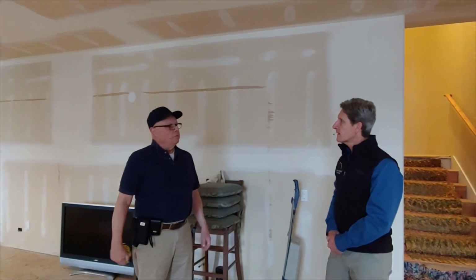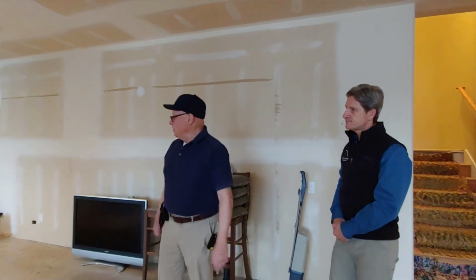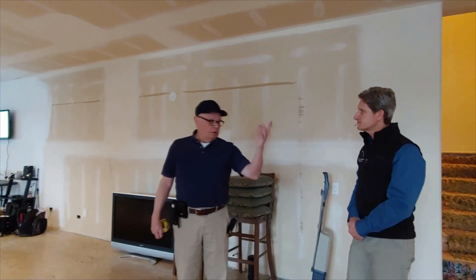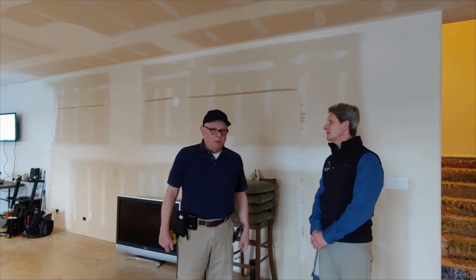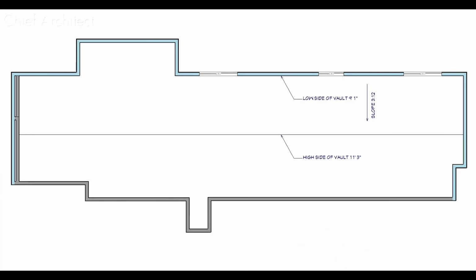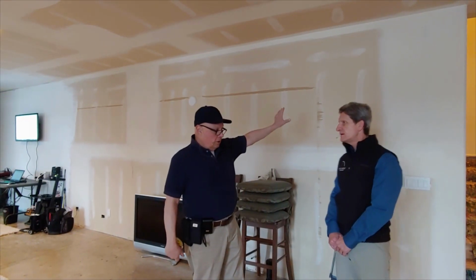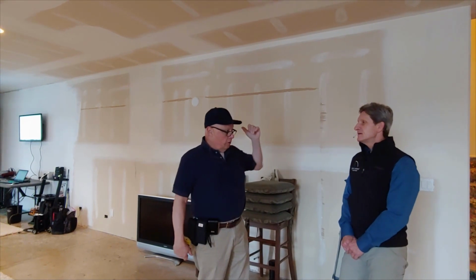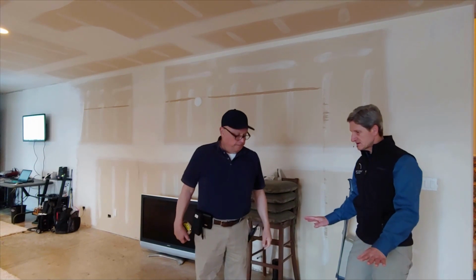That's obviously just put a tape on it or use your laser, put it on the floor, and measure up. In here, it looks fairly consistent. Some areas there might be a raised coffer or a tray. It might even be sloped. If I get a sloped ceiling, then I typically will measure the low side of the slope, finished, and if I can, the high side. But if I can't get the high side's measurement, then I'll use my level and just come over here and see if I can get the slope. Right. So the floor here is on slab.